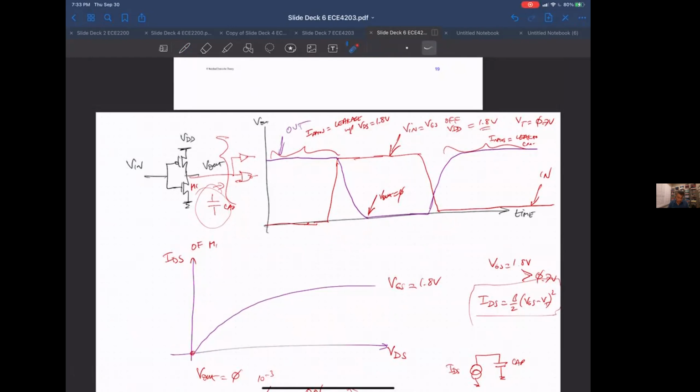The rest of the time, even when the transistor is on, because if the pull down network is on, the pull up network is off, theoretically there should be no current flowing through this on transistor. So after it's done transitioning, this on current doesn't really mean anything. And then vice versa. So the on current is only active during the transitions.